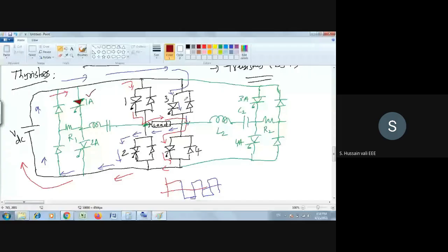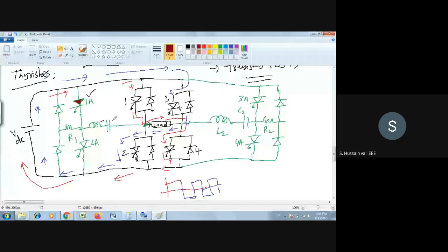Before this happens, there was actually a voltage across the capacitor. You will get the next half cycle, not now. You will understand how come there is negative here and plus here in the next half cycle. But for the time being, believe me that when 1 and 4 are conducting, the capacitor voltage is minus and plus polarity like this. And I turn on 1A.